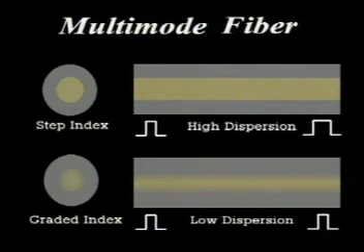In a graded index fiber, layers of glass with smoothly varying refractive indices comprise the core. Because the core center has the highest refractive index, the axial mode is slowed down, while higher order modes travel faster, so all modes will arrive at the end of the fiber closer together. This reduces modal dispersion, allowing long-distance fiber runs or higher transmission speeds.